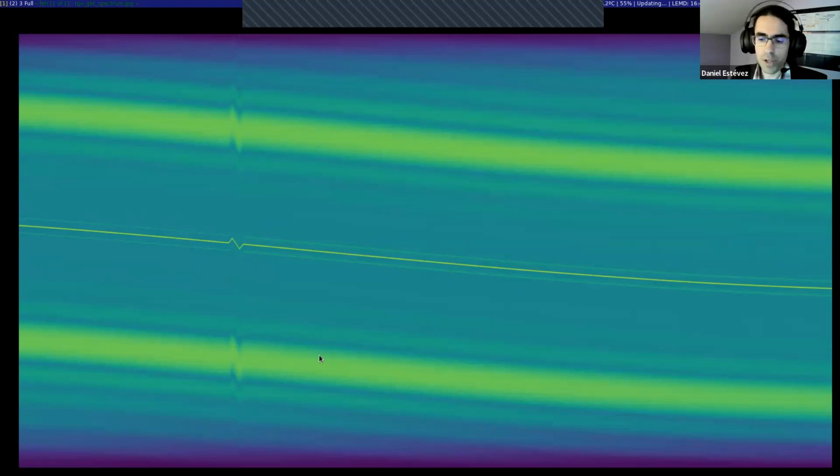And people have done shortcuts. They don't combine the subcarriers. They just look at one of the subcarriers. They do this Costas loop to correct for the effect of the Doppler, and they are good to go, basically.